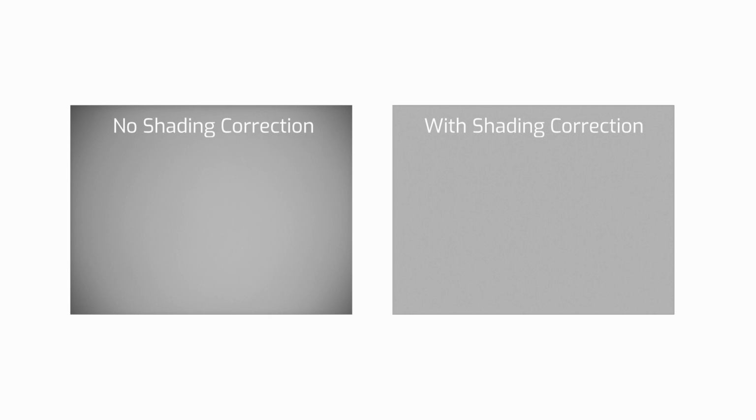This is partly to do with the quality of lens you choose for sure, but it's also because the tiny micro lenses that sit on top of each pixel, their shape is the same for each pixel. So for pixels that sit farther away from the center, their micro lenses are not shaped differently or tweaked to better capture the light that comes in at a steeper angle. So shading correction can be used to calibrate a gain boost in the edges for more uniformity across the image.